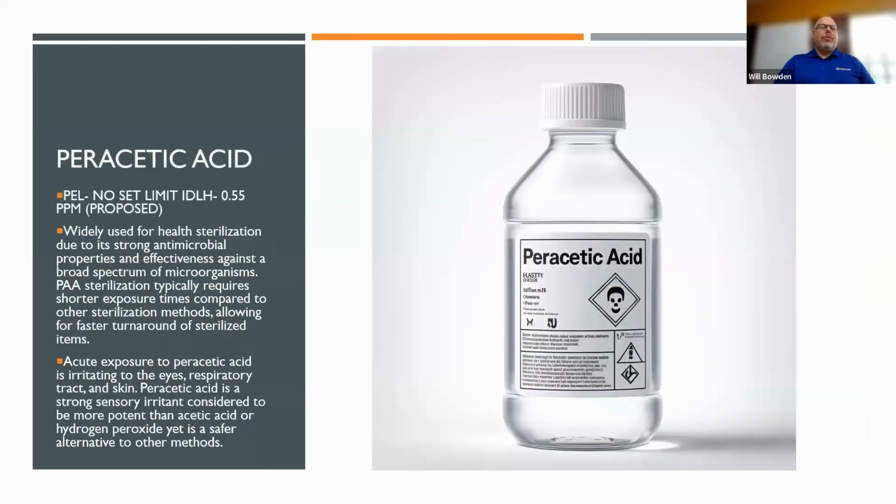And finally, we're going to focus on peracetic acid. In terms of a permissible emission or exposure limit, there's no set limit at the time. The jury's still out on that. There's still some discussions going on as to a permissible exposure limit. Immediate danger to life and health is 0.5 ppm, a proposed limit that is currently being reviewed by OSHA,